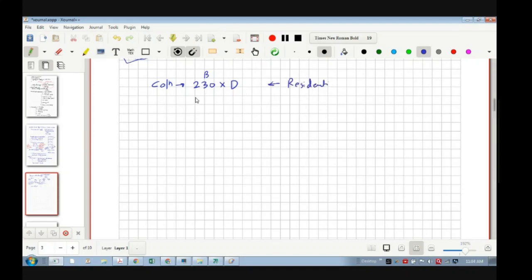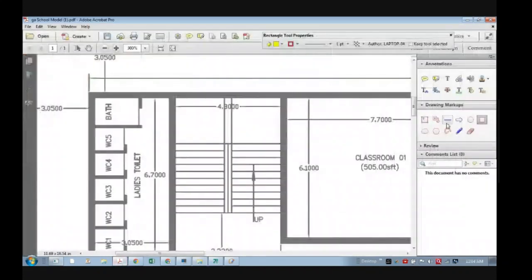There is more possibility that we can go with 300 also for the width of column for commercial buildings, school buildings, or whatever. You can take 300 mm, no problem, if it is required. But I would say you can start with this number. These are good numbers, why not start with this? So we will start with 230. 230 is our wall thickness, which means luckily our column will fit into this wall.